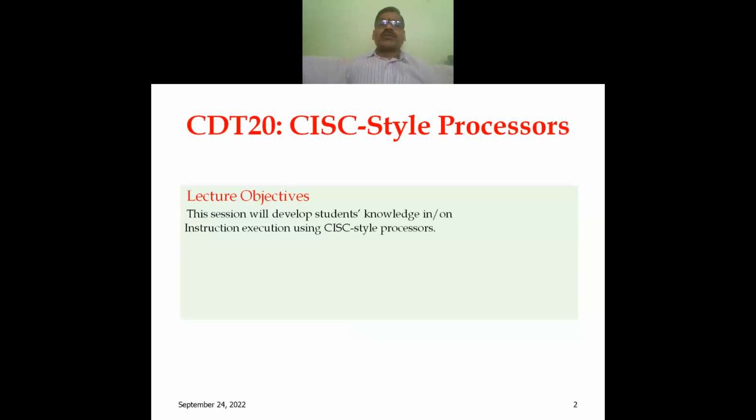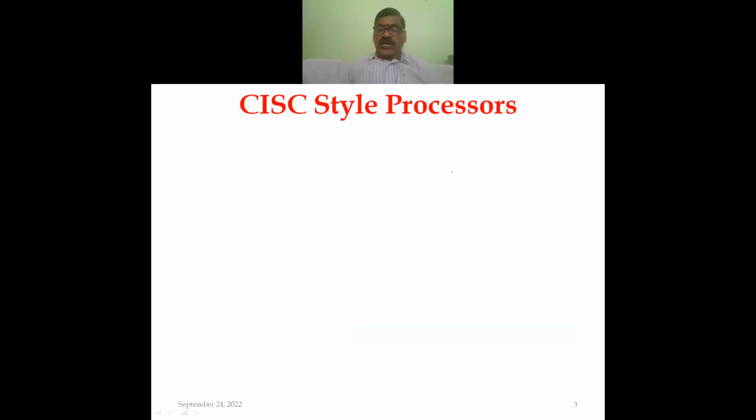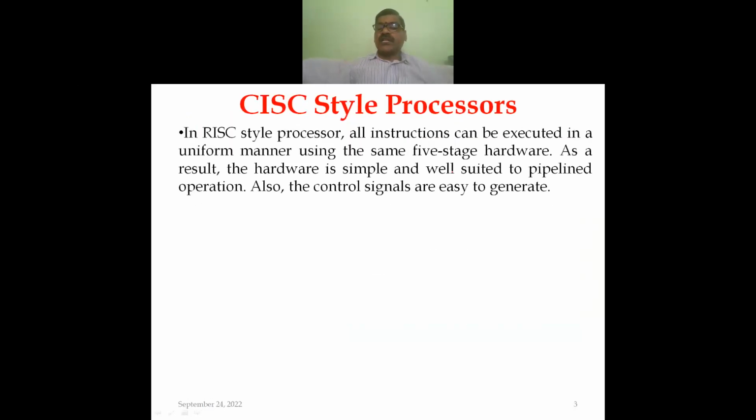So, CISC style processors. The lecture objective is that this session will develop the students' knowledge on instruction execution using CISC style processors. How we can execute the instructions, how the CISC style processors are different from RISC style processors, and how the instruction execution will be different, that we will see in today's classroom discussion topic.